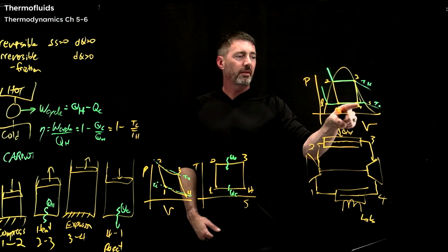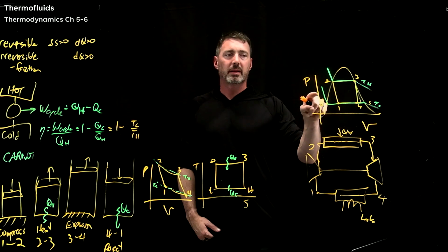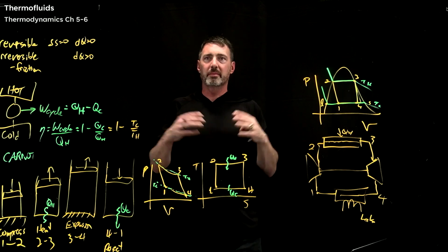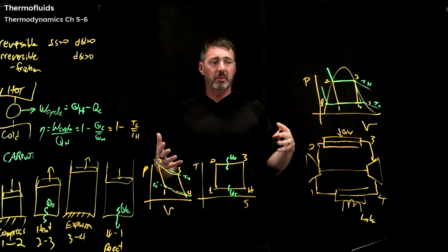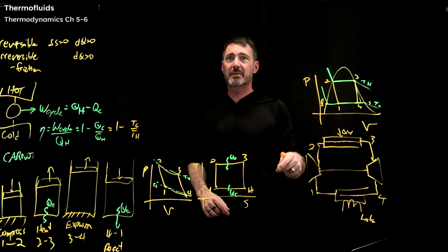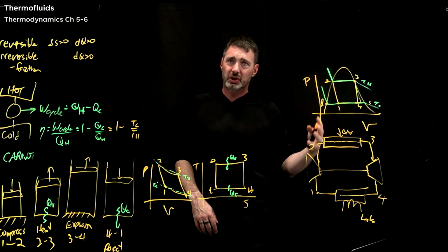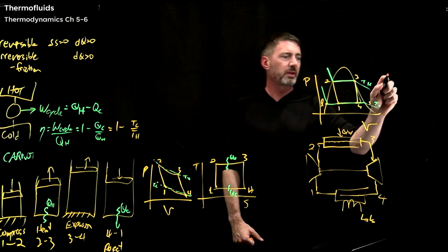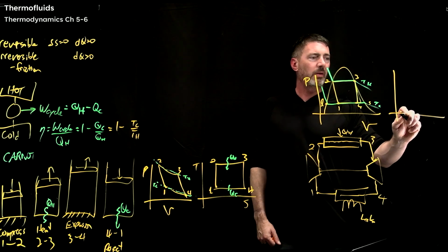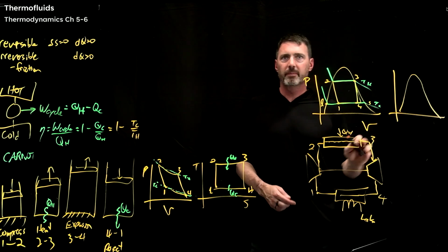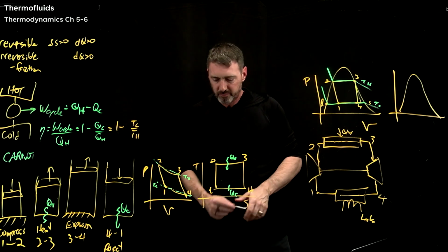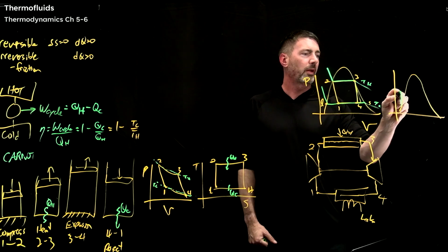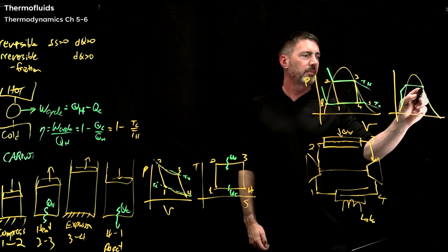And then same thing over here. If I come over here, I'm now maybe 70% liquid and 20% gas. And so this is a very bubbly liquid and I'm going to put that into a compressor, same sort of thing. That's just going to chew up the compressor. That really just destroys it. And so the reality of what you end up doing, and we'll cover this in a little bit, is that the system you end up drawing looks a lot more like this. Okay?